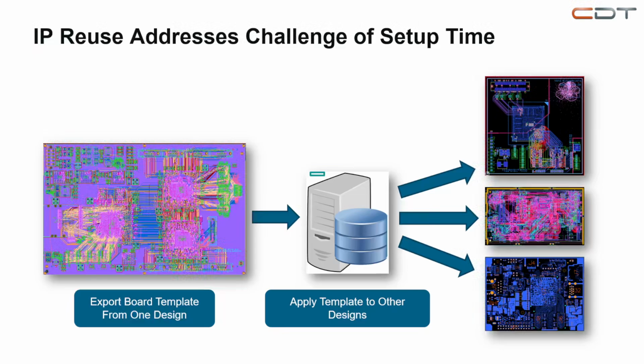It's quite intuitive in my opinion. You can copy and paste, drag cells down, make templates and do all sorts of things to speed up the process of filling these boxes. But the real challenging part is knowing what to put in those fields, researching your interface, reading the data sheets, and understanding the limitations of your fabrication process. All of that takes time.